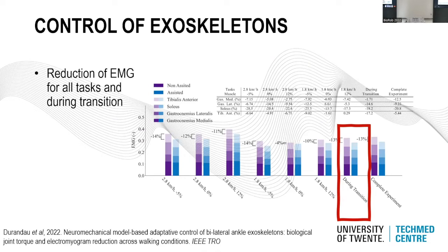So they can only assist during some predefined states where they know which kind of torque patterns they have to give back. But during the transition between those states, they don't have an optimal torque pattern assistance, so they cannot provide positive assistance. That's using our framework, since we are continuously computing joint torque, we can continuously assist the user.